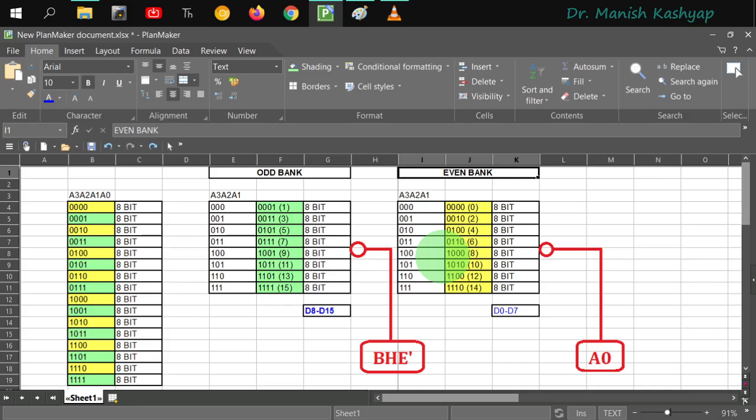The primary reason I will make clear a little bit later, but let us say that instead of using this single chip, we are using a combination of two chips, right? And how is the combination being used? Since we finally want addresses of 4 bits only, because by using these two chips we are trying to imitate these 4 bits, let me keep all the even addresses, shown in yellow, in one chip, and all the odd addresses, shown in green color here, in another chip, right?